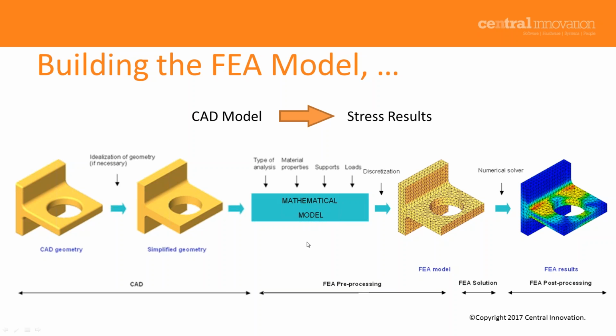From this point, we have to do the conversion, say this is my element size, and the software will do the mesh for you, run it, and then you have all the results in terms of stress, strain, displacement, factor of safety, etc. And you can review your design to see if it's performing the way that you like or there is a failure here.